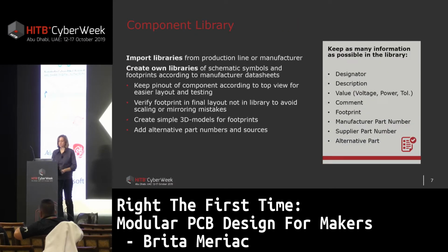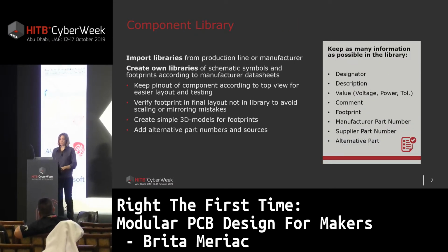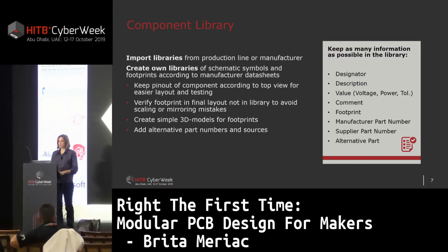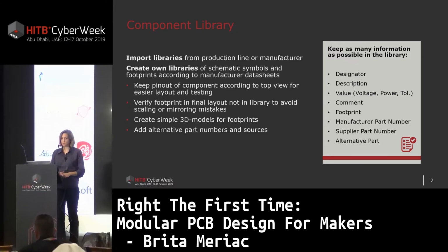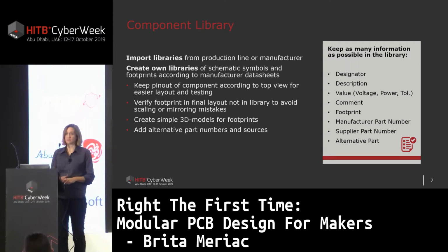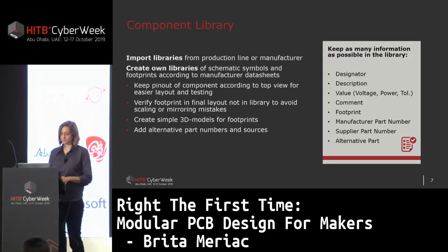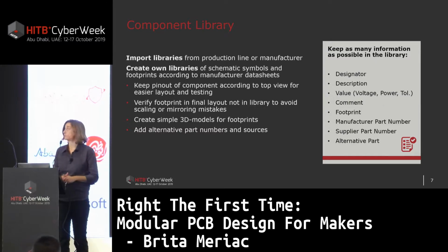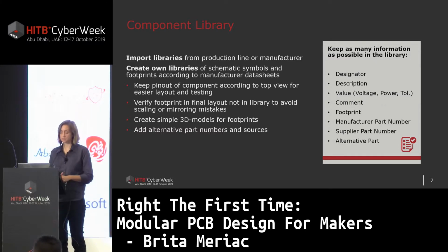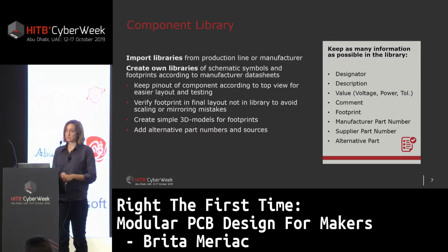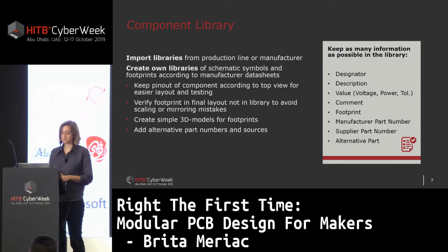Some manufacturers and production lines, like Seed Studio, provide their own component libraries. So you can download them and use them as a start, and then add your own libraries for the rest of the components. Again, follow the manufacturer guidelines and data sheets, and add as much information as possible in these library tables.